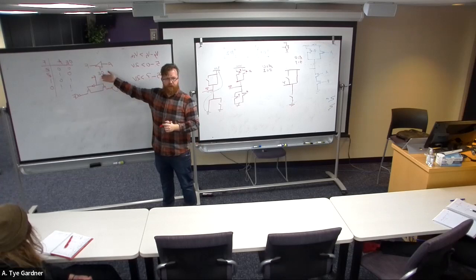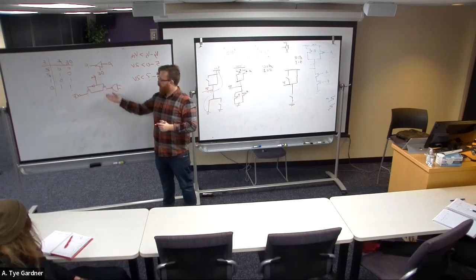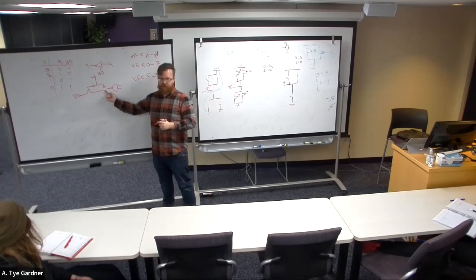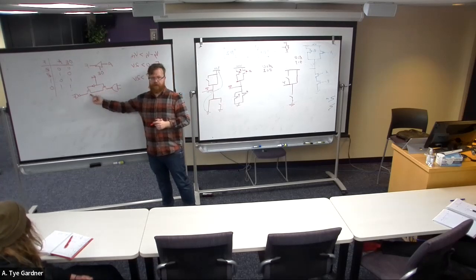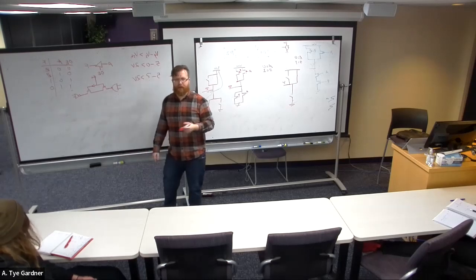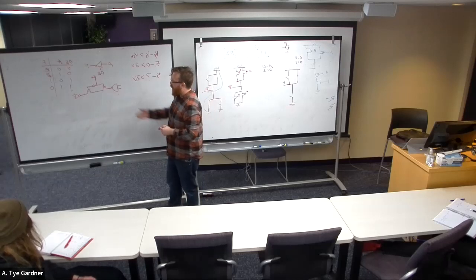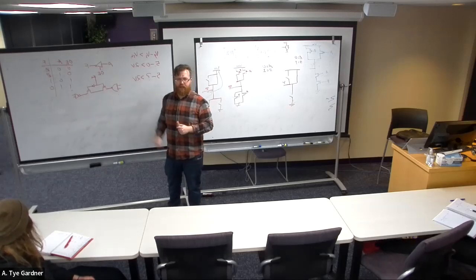So I have a signal called enable. In this case, a 1 is going to turn on this NMOS. This inverter puts a 0, that one is off. Only one of these can talk at a time. We've solved the problem, right? A little bit more elegantly. This is all an output enable is doing, basically.